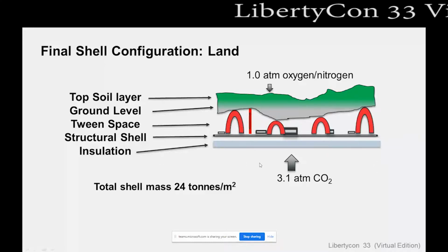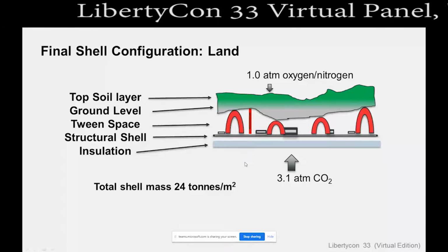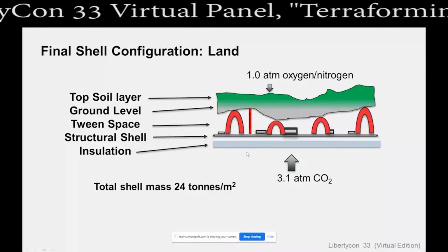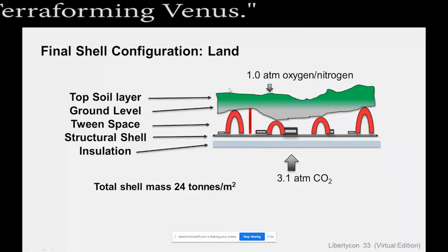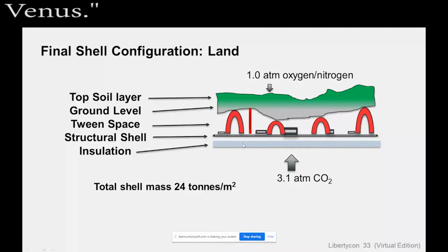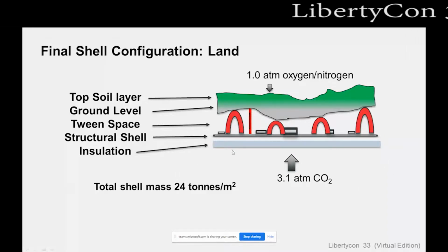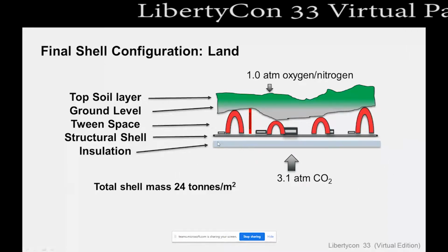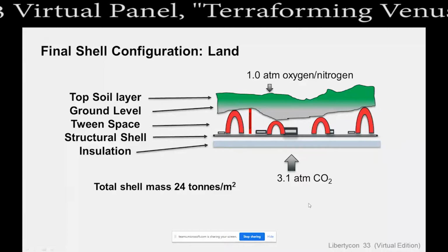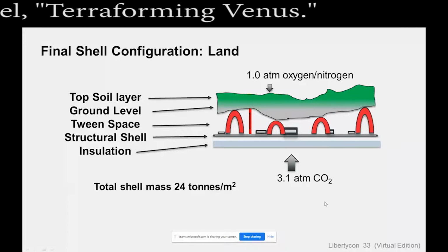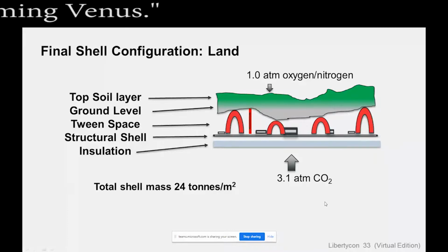Now again, it's about 91 C here, so we want to slow up heat transfer into the shell. So we're going to need a fair amount of insulation, and aerogel might be just the thing for this. Now this allows us to inspect the shell both top and bottom for any signs of corrosion and repair any problems as they develop. But again, this is just one possibility. There are many others.